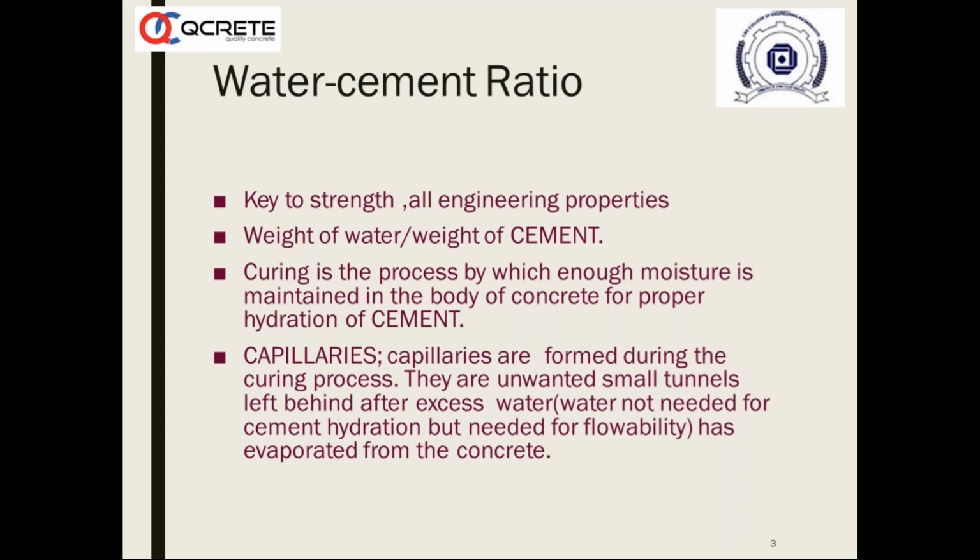The process by which you control the evaporation of water, the quick escape of water, is called curing. Curing is done by spreading polythene sheeting, or by ponding. Ponding is the most trusted and tested method. You make a concrete slab and fill up water on the concrete slab when the concrete hardens.